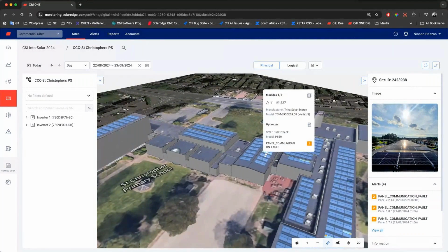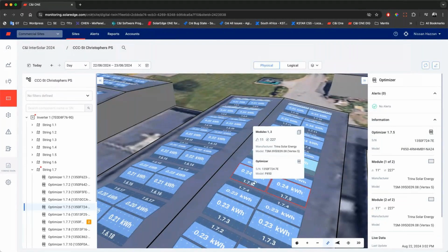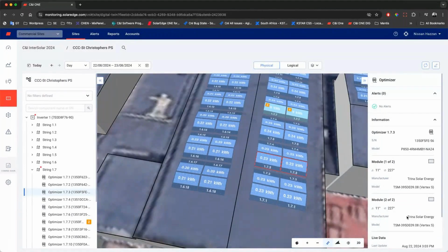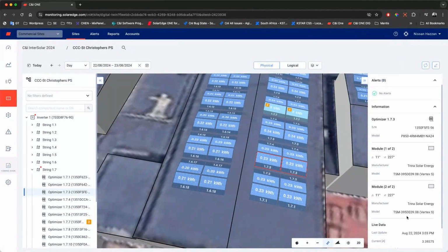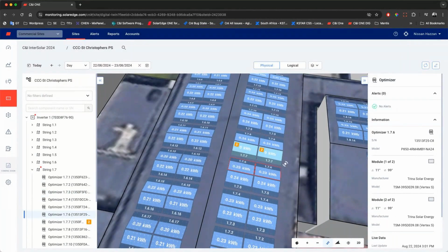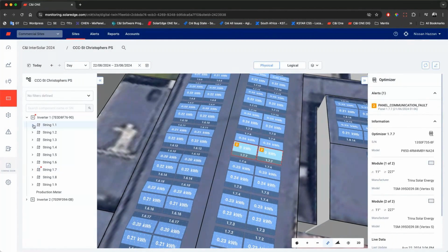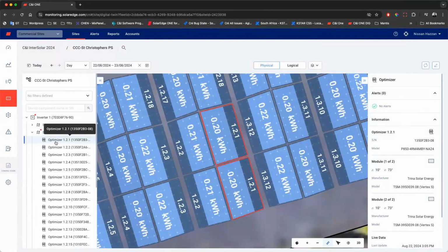This has live telemetry feeding it. So this is actually live values of what's going on the roof, on the optimizers. So you can use this to look at yield. You can use this to troubleshoot and find faulty optimizers. You can use this as a fantastic tool to guide installers to exactly the location of products which might need to be looked at. It might be a failed optimizer or a dodgy panel.